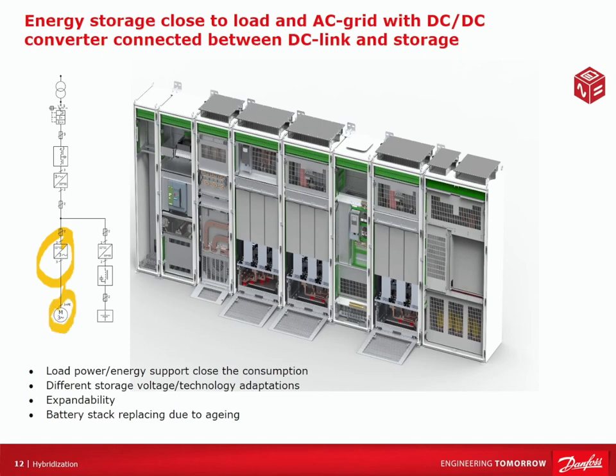I would have a battery storage here, but now I would connect that through here, which is a component, a DC to DC converter. Reason for doing that is that I have a common point of coupling right here between the hoist motor load and the DC to DC. And so if I want to essentially decouple these two loads, being able to control the charging and the discharging in the battery, I need to have this additional component, this DC to DC converter.